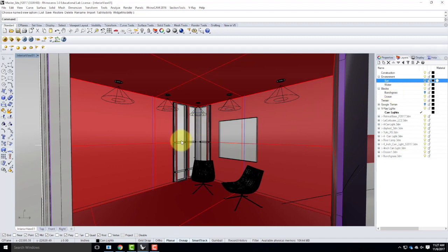If you used glass like the skyscraper glass, for example, on your exterior to get more reflective glass, switch it in the night view to a basic glass, because it's not going to render correctly if it's that highly reflective. A lot of you just use regular glass anyway, so I wouldn't worry too much about it, but I like to at least mention that.